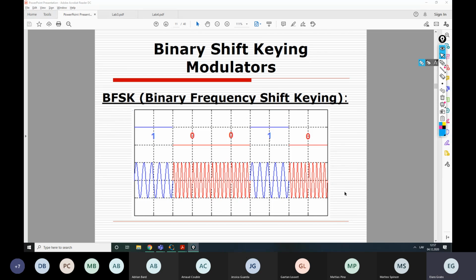Now, if we draw this signal, then it also looks like a frequency manipulated signal, meaning that for the signal value of 1, we have one value of the frequency, and for the signal value of 0, we have another frequency, right? So it's quite easy to visually notice the difference between these two frequencies because we have selected quite a large value k.